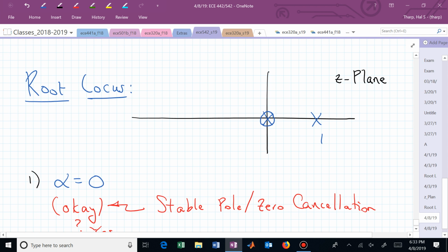So now on the exam, somebody says, oh, design a PI controller for this system. And the system was 1 over z. And you're going, really? He wants me to design a controller for that? Well, we did. We did a proportional, and we weren't too happy with it. Remember, it was minus 1/2 to the n, banging around, and we had a steady state accuracy problem. Now we're trying to improve that. So now I said, give me a PI controller. You go, okay, I pick alpha equal to 0.